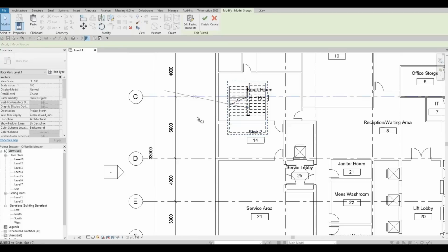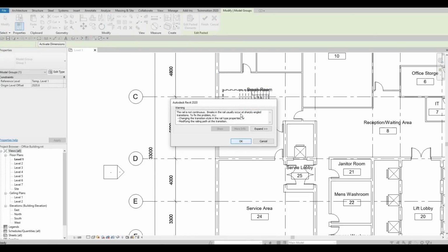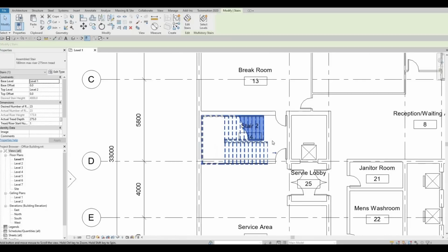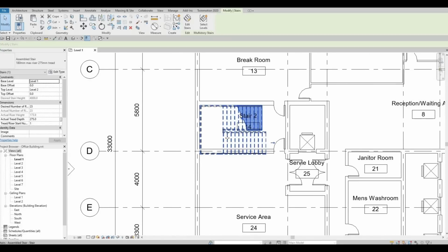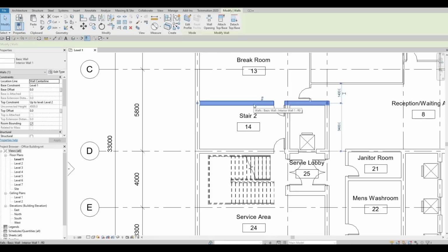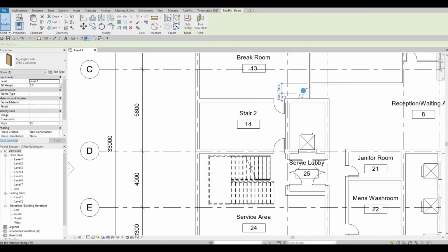and then rotate this. So I just copy that one and then move it here so that the second stairs is done as well. For the second stair, as you can see, we're kind of off with a couple of inches. So I'm gonna move it for now here and then move this backwards. So instead of 1400, I'm just gonna estimate it now to be moved. And don't forget to move the door as well because it will create an error.